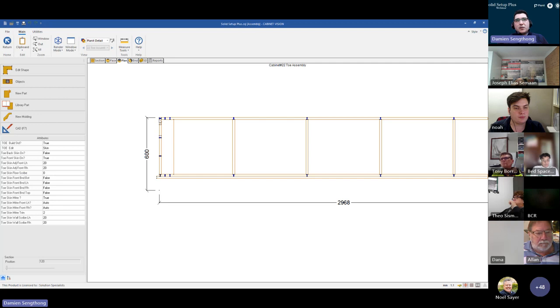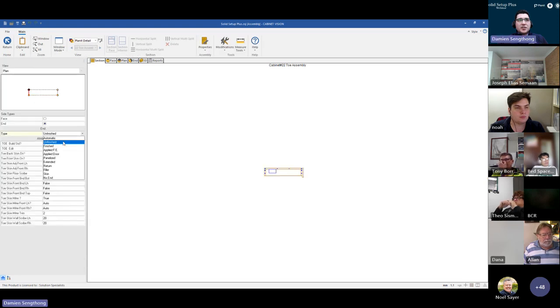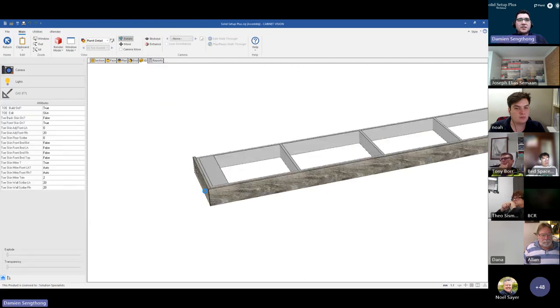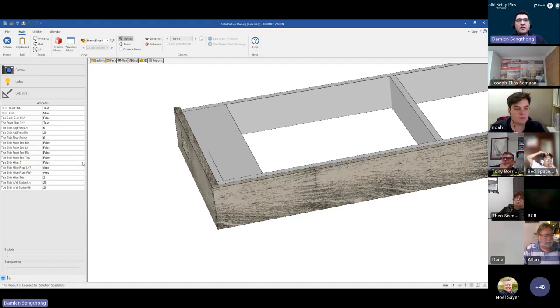Now, if you do have a return on your toe, so if I go to my section view, I'll change that to a finished. As you can see, it does supply a side finish toe here. Along with that, we'll provide you mitering options for the frames to be produced onto the machine. As you can see, we have our mitering options on the left-hand side. So toe skin miter. So if you don't wish to dual miter, you can turn this off, which will then convert it to a butt join configuration.